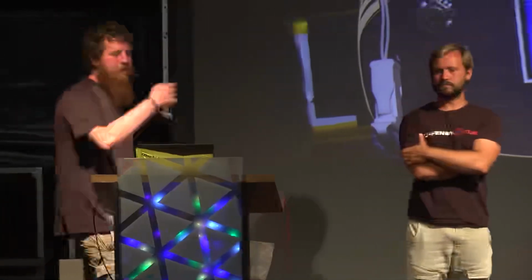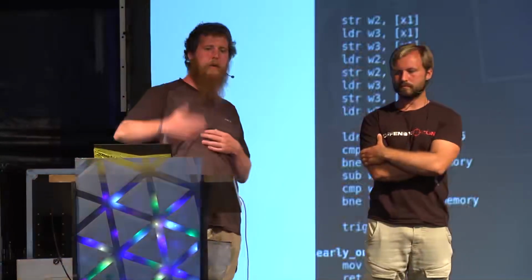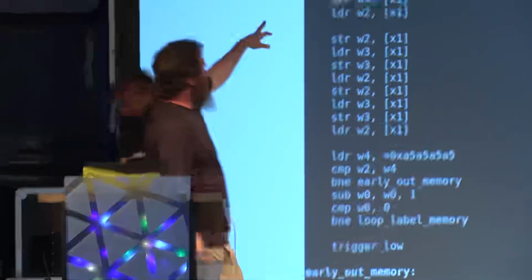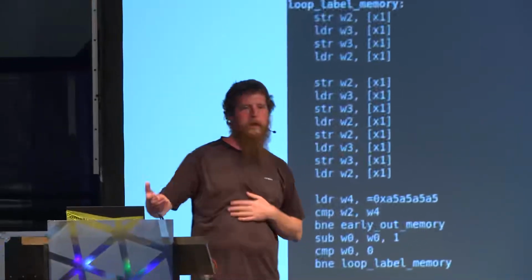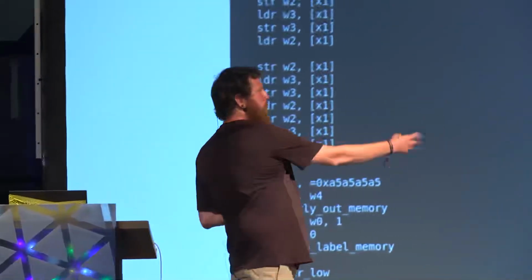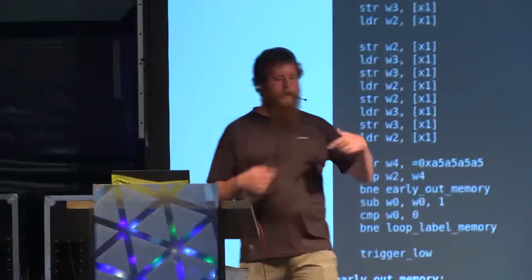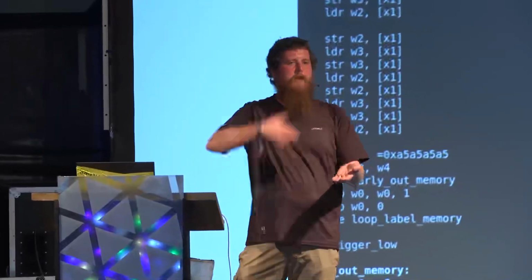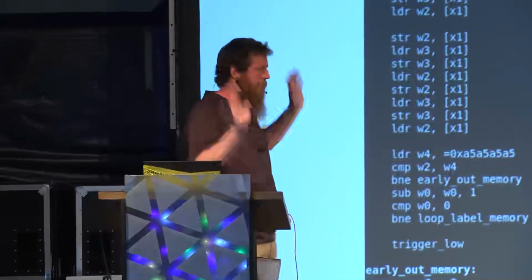I thought the slides were up there. So what we will usually do, in this case where we had complete control over the target and the code running on it, yes, this here, the line that says trigger high, that basically just sets one of the many GPIO pins, it just drives it high. From when we saw the setup earlier, there was a box on the right that was controlling all the rest of the hardware. That will wait until it sees that trigger, and then it knows to, after a fixed amount of time, deliver the glitch. So in this case, we can just set a GPIO, so that's easy and that's fine.